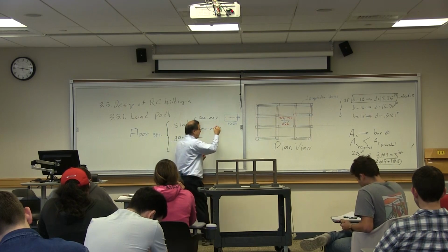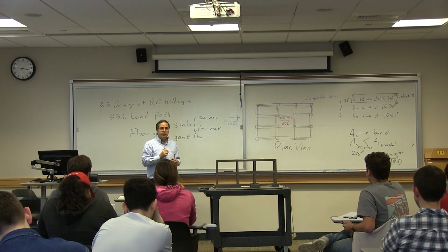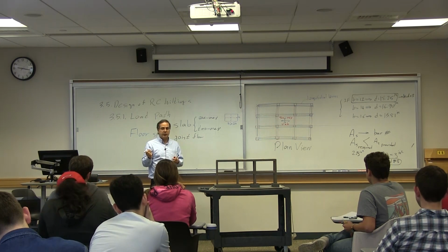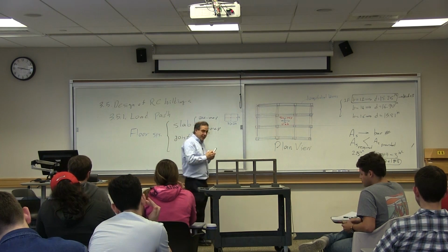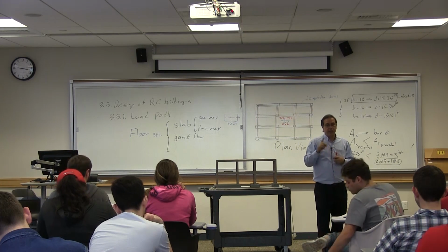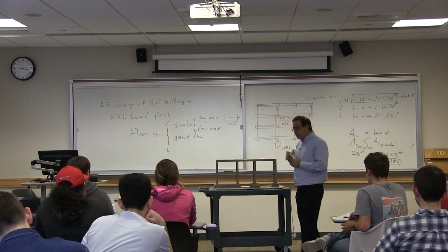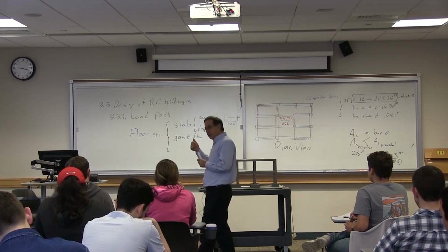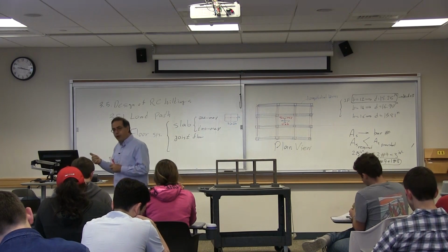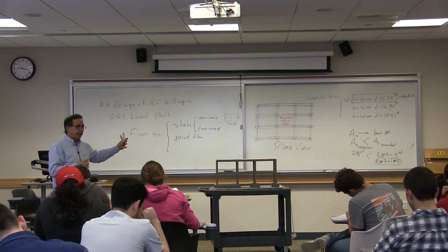And if I ask you how much did this line deform, the answer again is 1 inch. Therefore, it is not quite that their deflection is different. In fact, the reason the load goes in the stiffer direction more is that their deflections are equal.